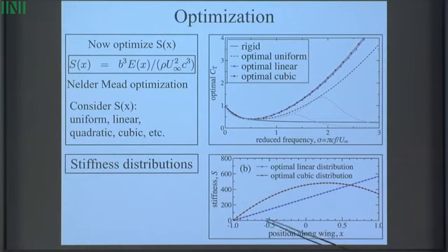Both of them have low stiffness at the leading edge and higher stiffness further back, which means that focusing the flexibility near the front, near the root of the wing where it's being forced, seems to give an advantage in thrust. If you see that trend, you might ask, what's the most extreme version of that? And that goes back to the torsional spring case that I showed earlier.